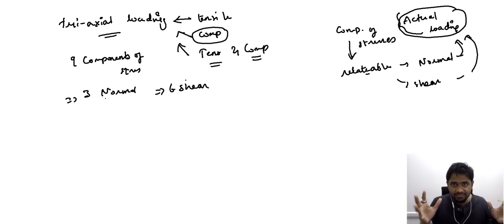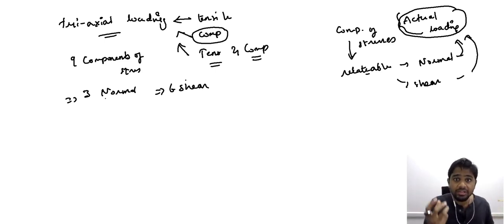We have seen the convention for tensile and compressive stress: a tensile stress should be positive, and a compressive stress should be denoted by a negative sign. Correspondingly, a stress component with a negative sign essentially means that it emerges from a compressive load. Therefore, it is possible for us to have a generalized description of the loading condition.